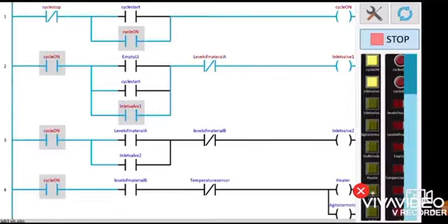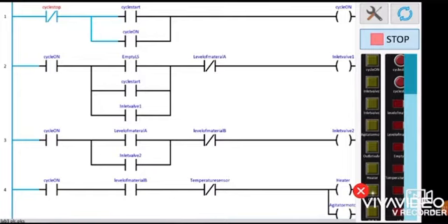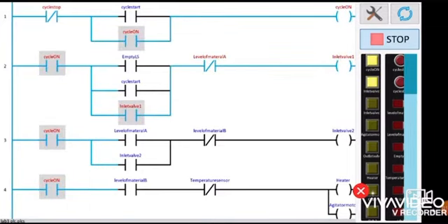First, let's look at the first network. When the push start button is pressed, there is current flow. You can refer to the blue line for the current flow. That indicates the current. Since I pressed the push start button, there is control. If I release the button, the system is still going on. This is because the function of the latch is to continue the operation even after the push start button is released. So in order to stop the current flow at the first coil, what we need to do is press the push stop button. After we press it, the current will be blocked.